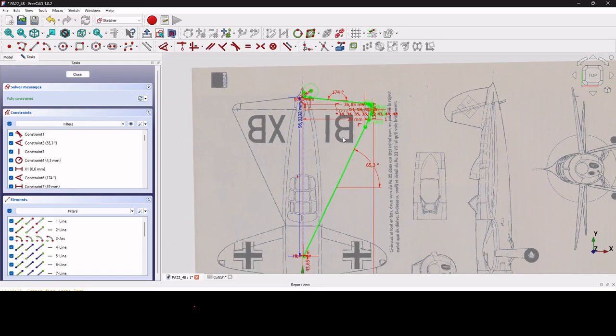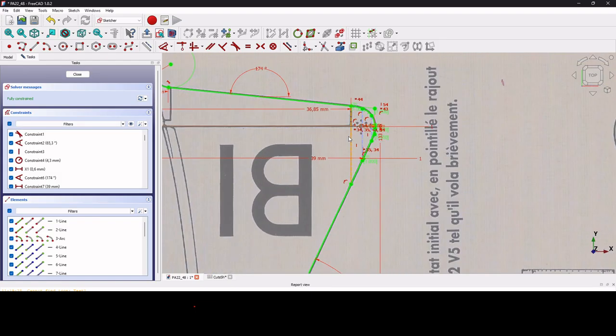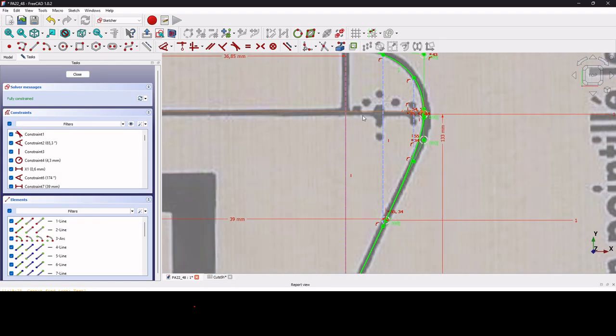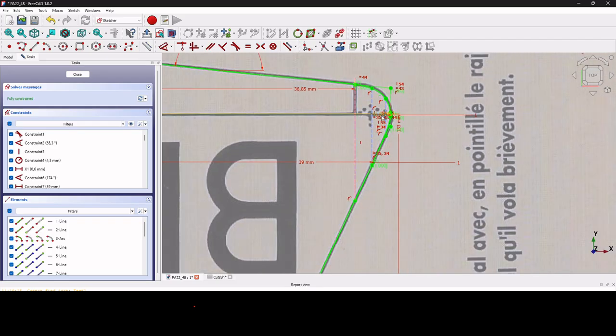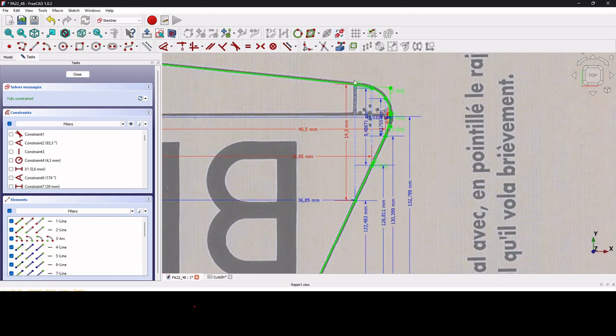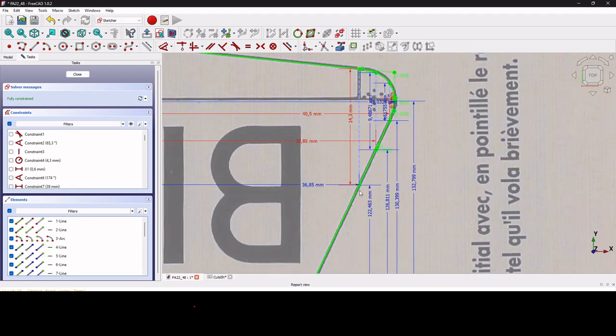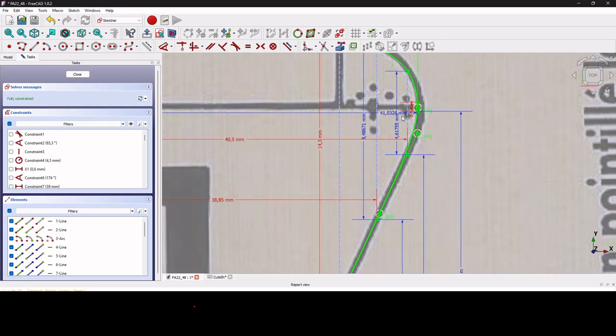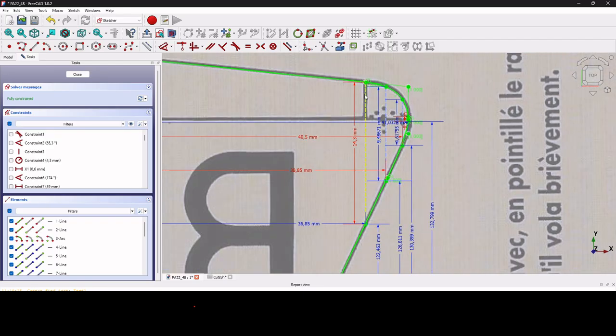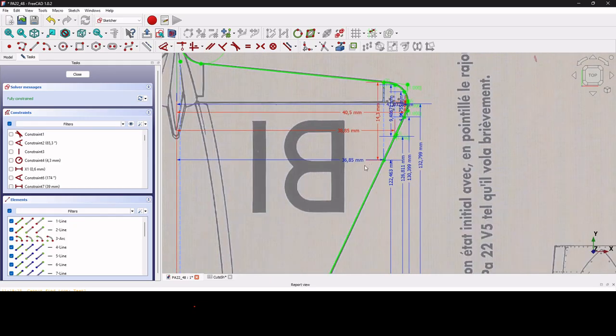Now, once I've done that, a little bit like I'm using the YZ skeleton, in fact, I'm using that as the basis of the different cuts that I will use again in my wing. So first of all, I'm using the virtual space. If I click on here, you will see that I've kept all the constraints about my different cuts here. Usually, you need 4 cuts in order to do a kind of round shape like that using a loft. So that's exactly what I've done here.